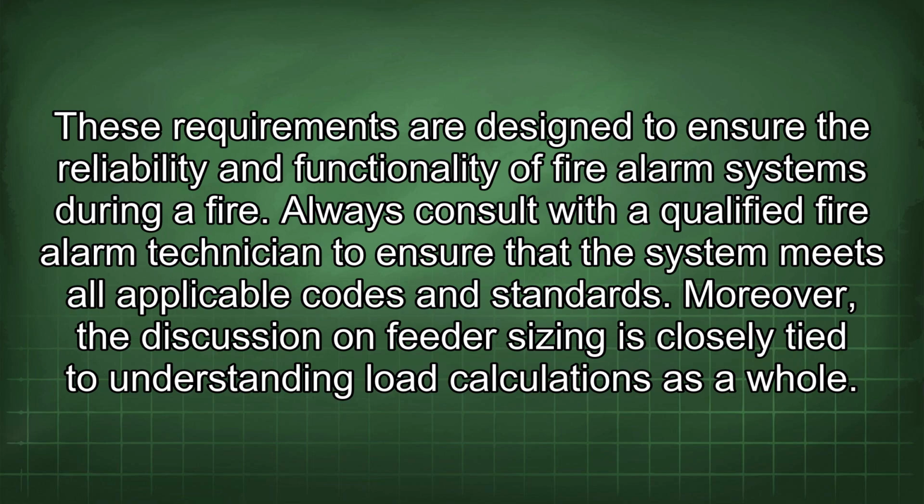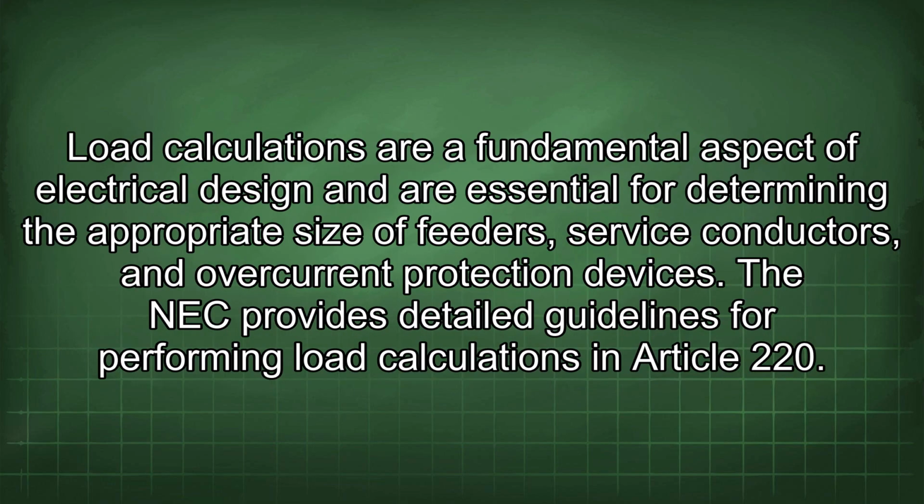Moreover, the discussion on feeder sizing is closely tied to understanding load calculations as a whole. Load calculations are a fundamental aspect of electrical design and are essential for determining the appropriate size of feeders, service conductors, and overcurrent protection devices. The NEC provides detailed guidelines for performing load calculations in Article 220.